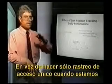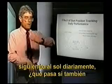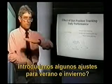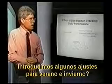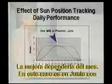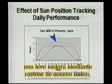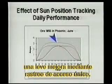Instead of just doing single-axis tracking, where we're following the sun on a daily basis, what if we also introduce some adjustments for summer and winter? That would depend, the enhancement would depend on which month. In this case, we're looking at the enhancement in June being a slight enhancement over single-axis tracking.